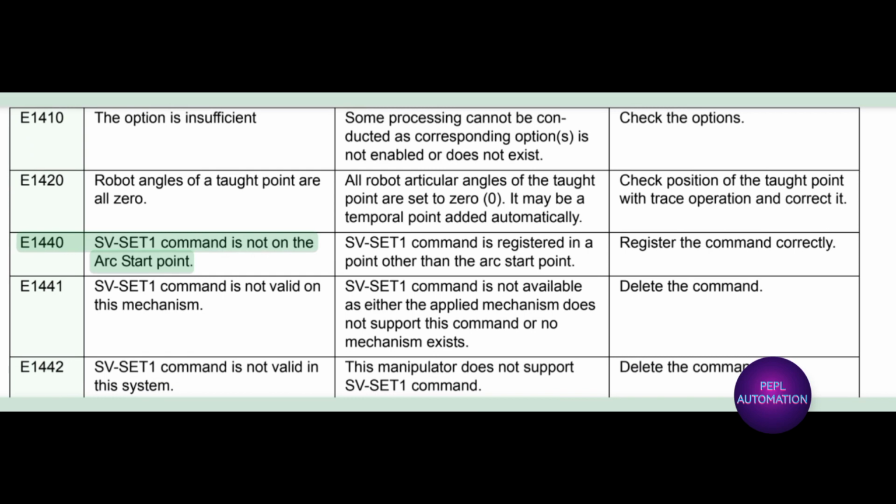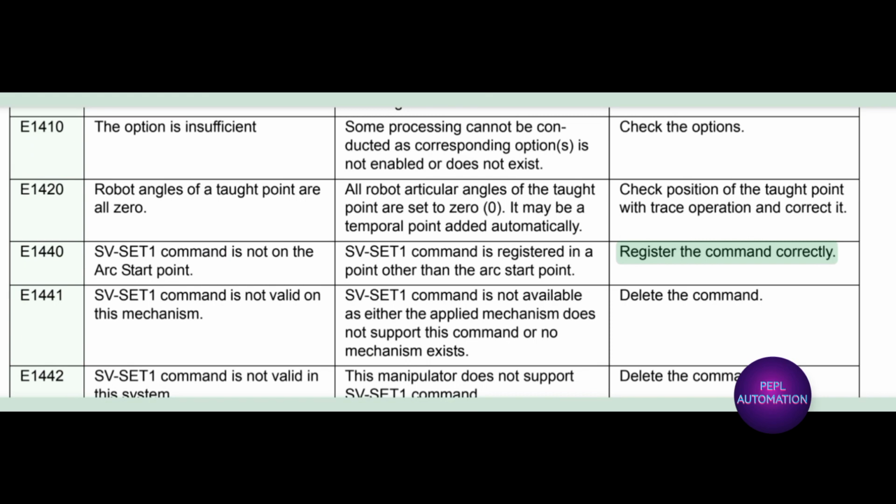E1440 SVSET1 command is not on the arc start point. SVSET1 command is registered in a point other than the arc start point. Register the command correctly.